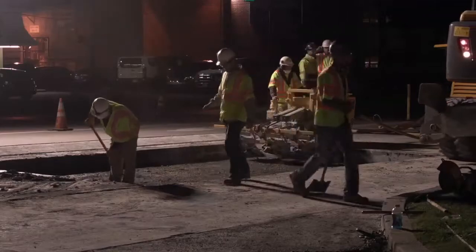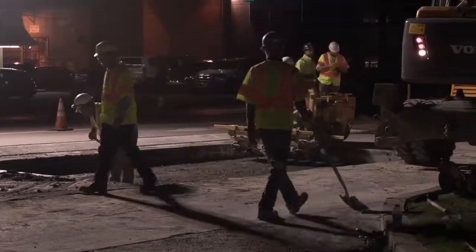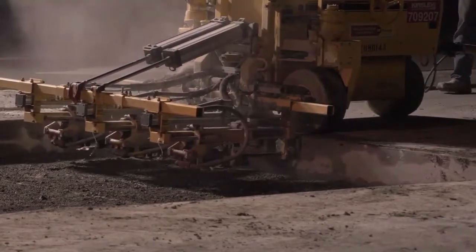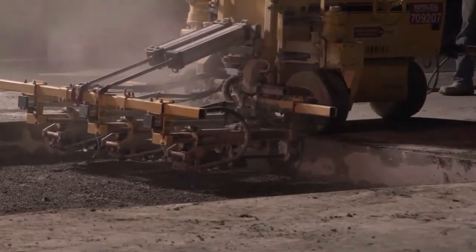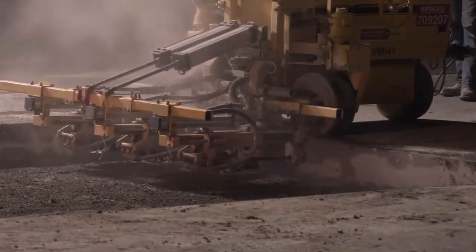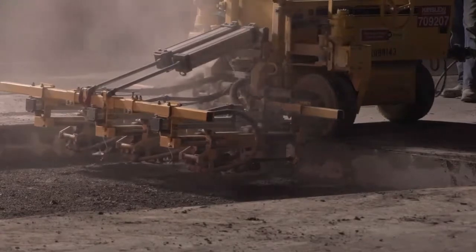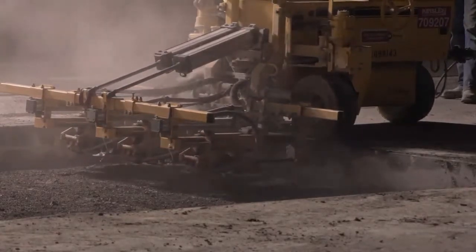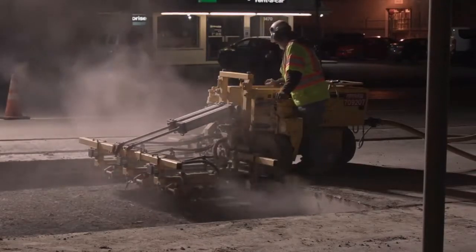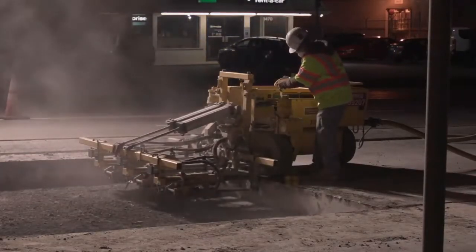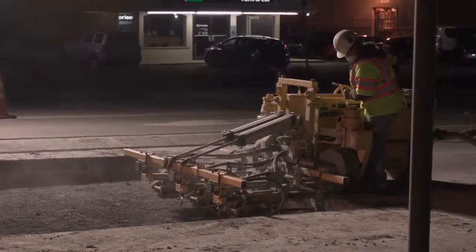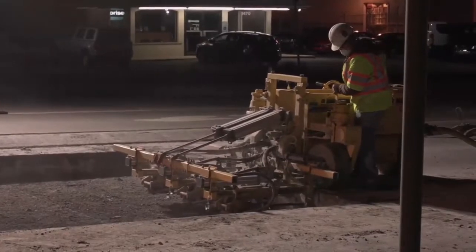Load transfer provisions. Drilling recommendations. Dowel holes are drilled into the face of the existing pavement on 12-inch centers across the joint face at half the existing pavement depth. No tolerances allowed. Drill dowel holes slightly larger than the diameter of the dowel bars. Use frame-mounted gang drills, no hand drills or drills that rest on base. Hole location may be moved transversely by plus or minus 1 inch to avoid existing reinforcing steel.